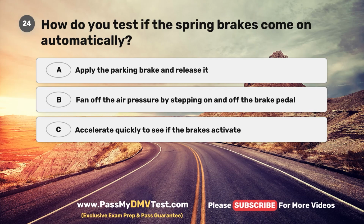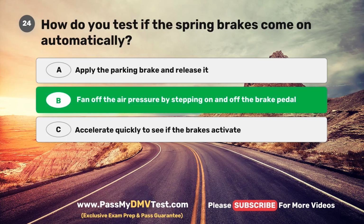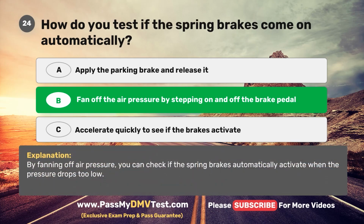Question 24. How do you test if the spring brakes come on automatically? A. Apply the parking brake and release it. B. Fan off the air pressure by stepping on and off the brake pedal. C. Accelerate quickly to see if the brakes activate. The correct answer is B. Fan off the air pressure by stepping on and off the brake pedal. By fanning off air pressure, you can check if the spring brakes automatically activate when the pressure drops too low.